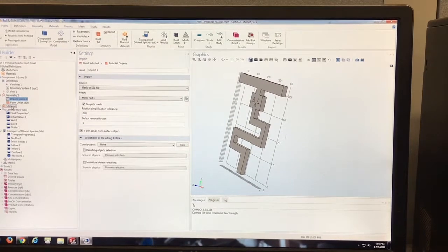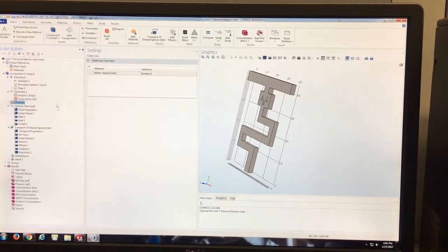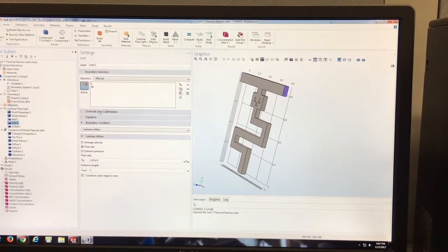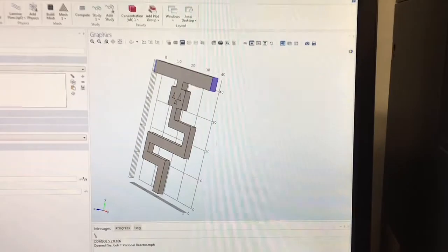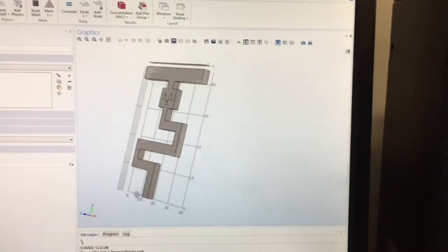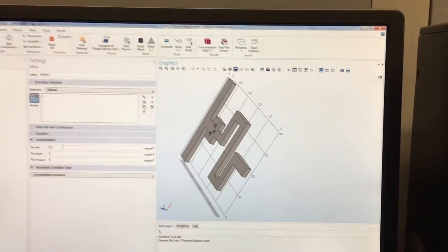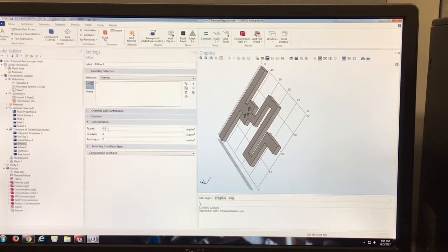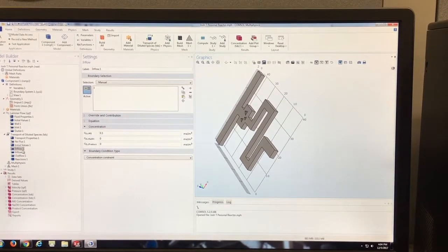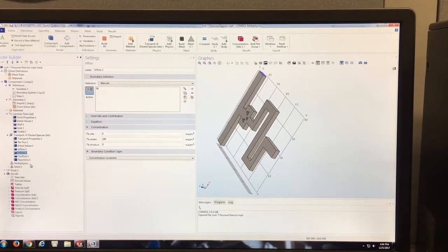For materials, we're going to be using water, liquid as our model. You're going to want to set some things, for example, the 2 inlets on your reactor and the outlet on your reactor, the inflow, which contains the concentration of the reactants that are going to be entering your reactor, 0.5 mole per meter cubed for malachite green and 100 mole per meter cubed for sodium hydroxide.